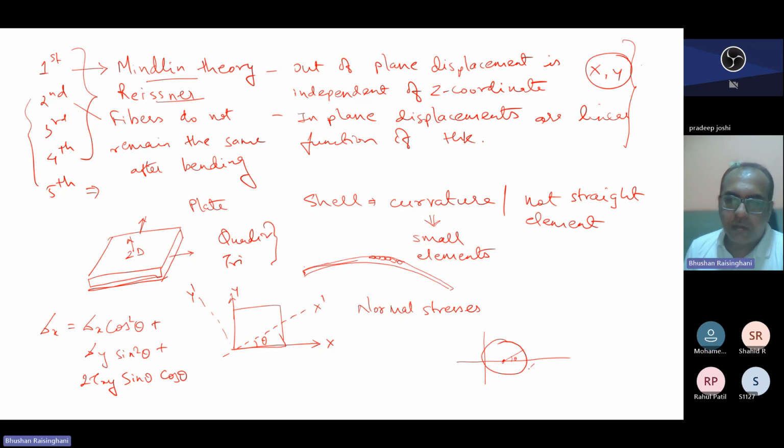So this is your sigma x, this is minimum sigma y. From that you derive the stress for this particular point, which is at an angle theta. Based on that, all these derivations are there using the Mohr circle. So they all apply here for the derivation purpose, and you should be thorough with the first fundamental principles before using it for your particular purpose.